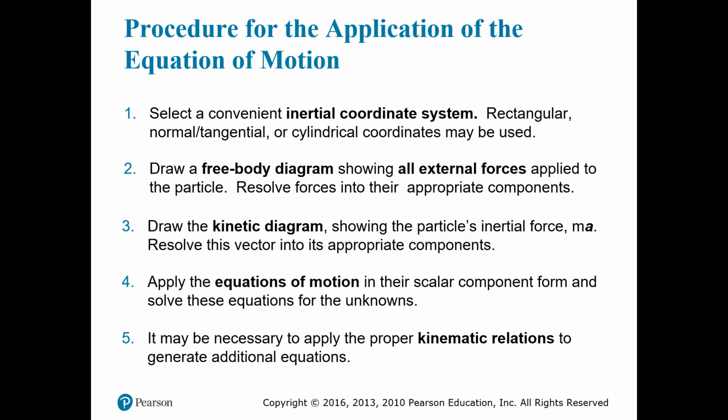So how can we put together a procedure in order to do all of the exercises? And this is quite important. Again, very similar to statics, super similar to statics. So first of all, you need to establish an inertial coordinate system. You know, rectangular, normal, tangential, or cylindrical will be used.